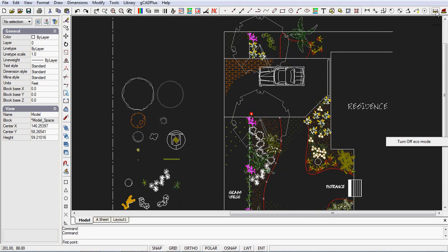We'll say distance, but this time we'll come down here into the left hand toolbar and snap to endpoint. So you click it and move back, and you'll find then that the cursor will just jump to that corner and give you a little orange-brown locator. So we accept it. We don't have to put the cursor right on the corner. It will jump to the corner. And then we can move to the boundary, and what I'd like you to practice is right-click at that point.